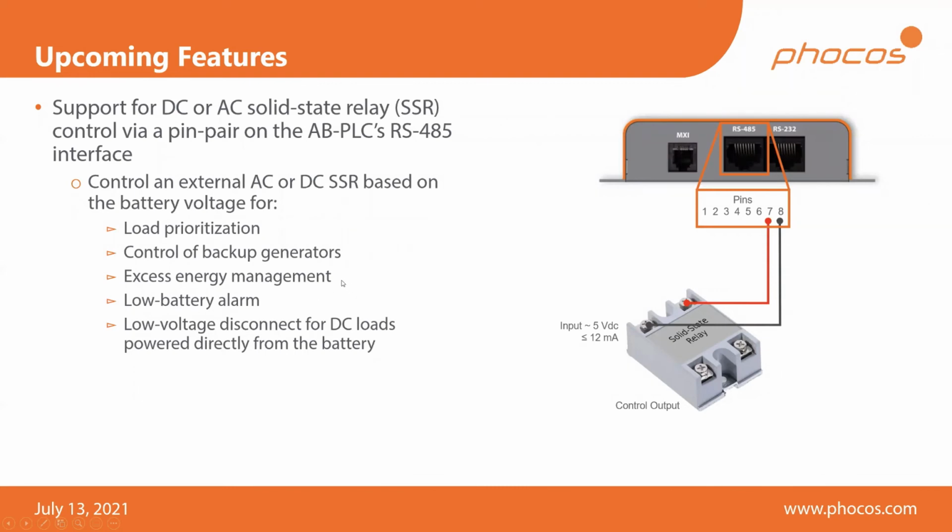Then the point in the middle, we have the excess energy management. As I mentioned at the very beginning of the session, especially if you're in an off-grid situation, there's no way to sell power, right? If you're off-grid, then by definition, you're not connected to a public grid. So there's no way to sell any excess energy that you might be producing from your PV array to anybody else, to the public grid, because you're just not connected. So the next best thing is to do excess energy management.